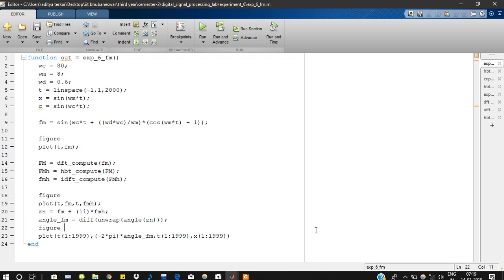As stated earlier, given a complex number x plus jy, the phase of that complex number can be defined as tan inverse of y by x. We perform the same thing in the case of signals. Now that we have a quadrature phase shifted signal, which is orthogonal, like y in x plus jy, the phase of this signal can be determined as the ratio of your quadrature phase shifted signal to your original signal, and you take a tan inverse of it. In my case, I have implemented that in this way.